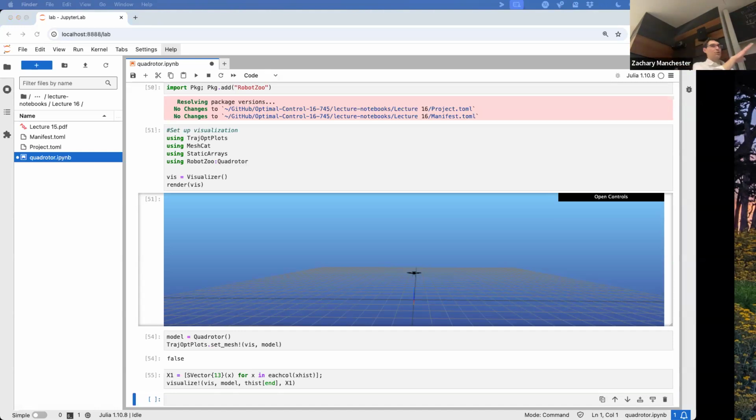If you play the quaternion tricks right, and you do these body frame error state tricks with the velocity in the body frame, et cetera, it's insanely robust to really huge errors. So if you wanted to do wild aerobatic stuff, what you would probably do is have a slightly higher fidelity model that captured some more of those aerodynamic terms.